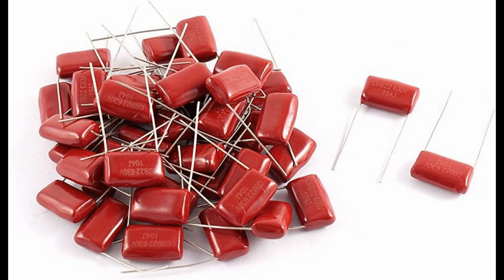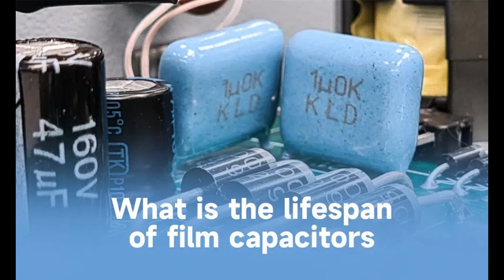6. Self-healing mechanism in metalized film capacitors. In metalized film capacitors, a self-healing mechanism exists. When a high voltage creates a localized dielectric breakdown, the thin metal layer at the point of failure vaporizes, isolating the defect without affecting the rest of the capacitor. This self-healing property ensures continued operation and prolongs the lifespan of the capacitor.